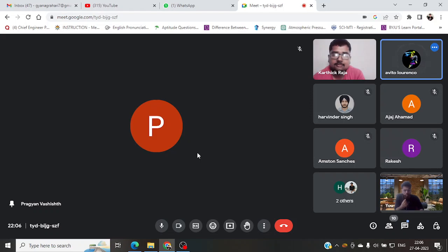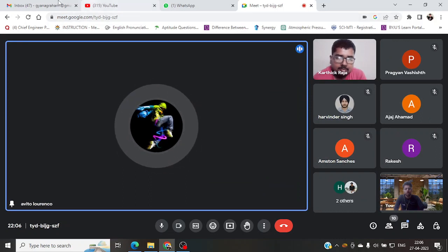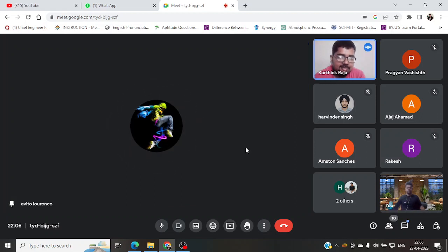Just the first question. In ultrasonic testing, we don't waste any material. For example, in dye penetration you have the dye, then you also have the cleaner and developer, and all of those sprays that we will be wasting, and those sprays are highly toxic. So why do we still use that on board a ship if I can just use a very simple ultrasonic test? Well, good question.